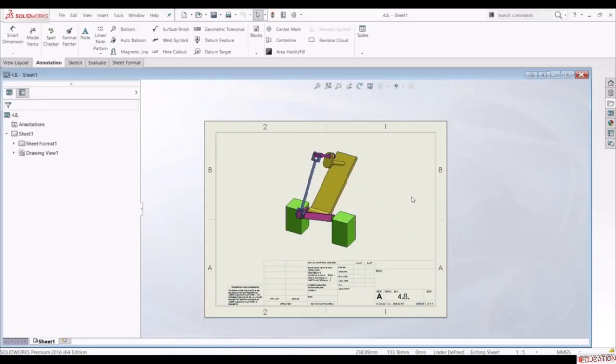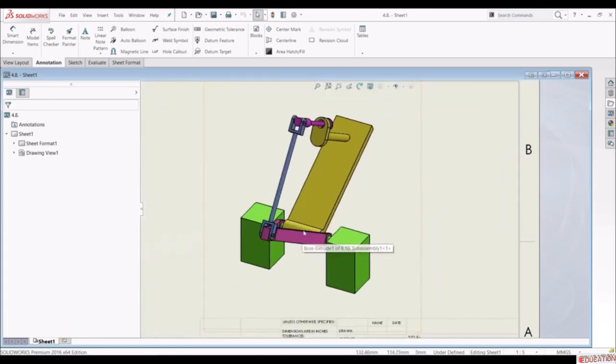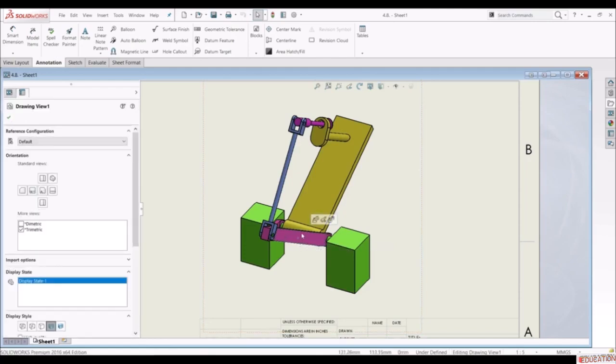In this lecture, we're going to show how to use linked nodes. We can link displayed nodes to a previously defined custom property or to a website. For example, we have to find who is the author of this component, this one. To accomplish that, we can use linked nodes or we can use a bill of materials table. We're going to show both ways.